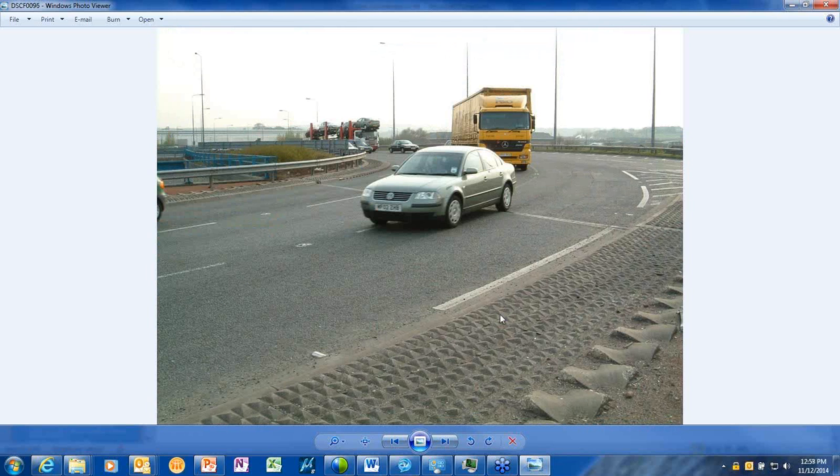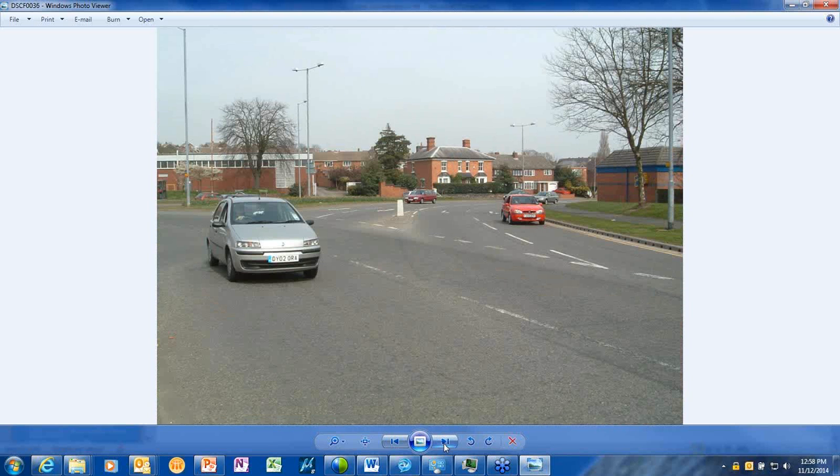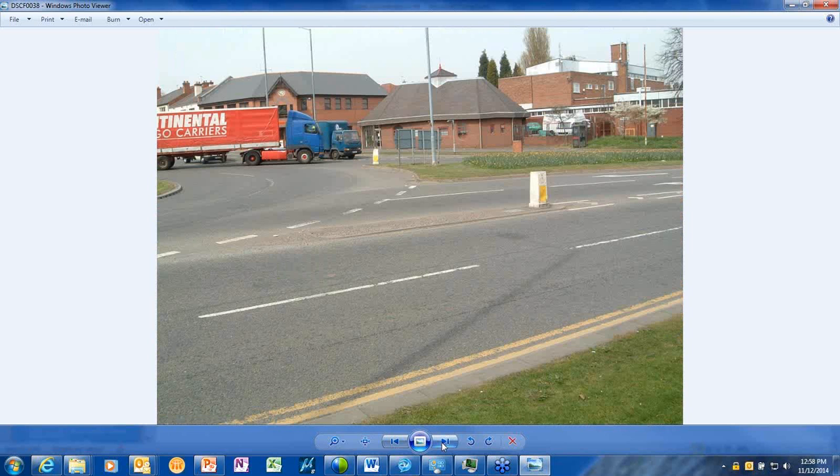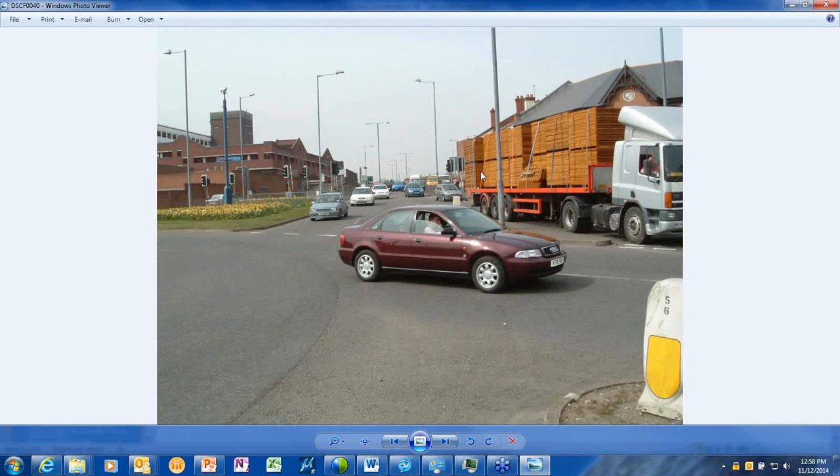I think we're going to start to see this more and more, because we have truck drivers at roundabouts. I'll show you in a few slides some of the designs, but they're getting pretty sloppy with their use of just overtracking the curbs on the outside. And even where we provide a good accommodation of the trucks, they're quite sloppy with it. We go on trips to the UK and learn a lot about roundabouts. They have big trucks there too. The cabs aren't as big, but the trailers are big.